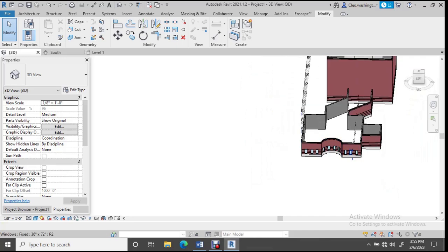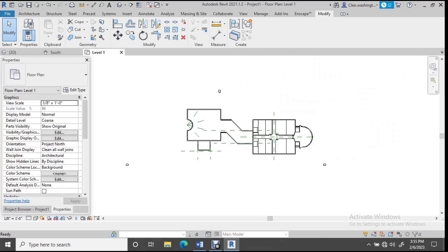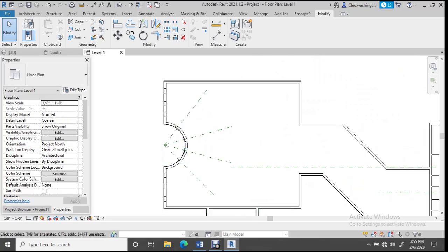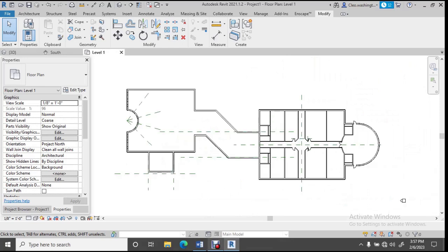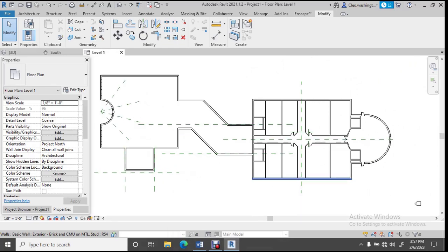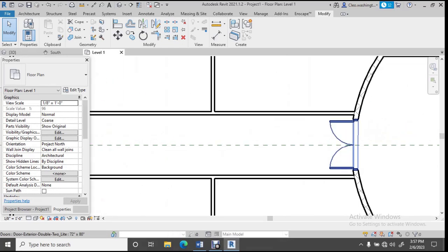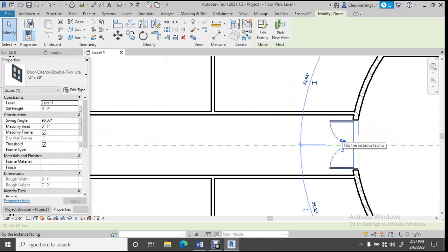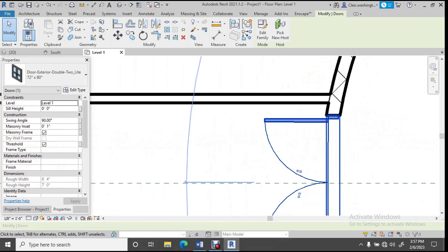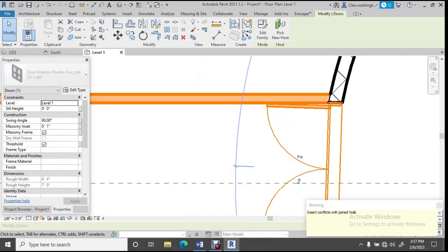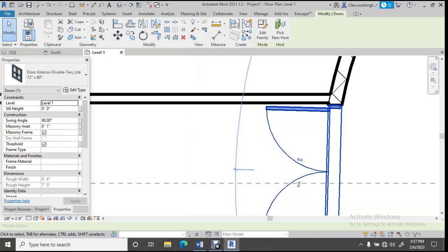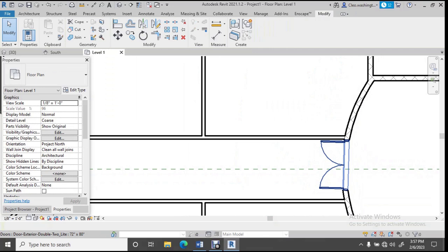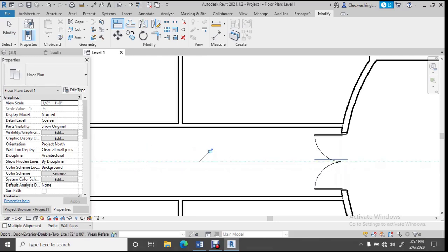west wing, okay? Now, let's go back to your floor plan, and you should be able to see the windows there as we left them. Okay, let's revisit that align tool. Let's go ahead and say we move this door up a little bit. And you want to have this door aligned on that wall. So it's the same principle that we utilized on the window. You want to type in AL, okay, and select the reference plane, and then select the center point of the door, and it will align to that reference plane, okay?